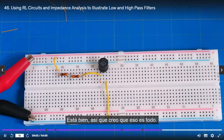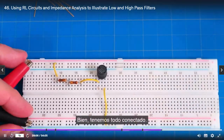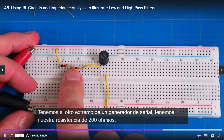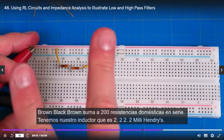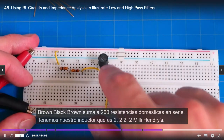Okay, all right, so I think that's it. There's nothing else to it really, right? We got everything hooked up. We've got our signal generator, the other end of the signal generator, and our 200 ohm resistor. Brown, black, brown times 2 is 200 ohms. Resistors add in series.